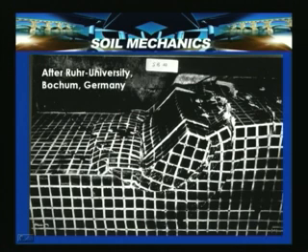In this case, a typical slope failure is shown here, a physical model. This is after University Bochum, Germany, where you can see a typical slope failure and the formation of cracks. These are tension cracks, and this is a typical slip surface which is formed in a homogeneous clayey soil.